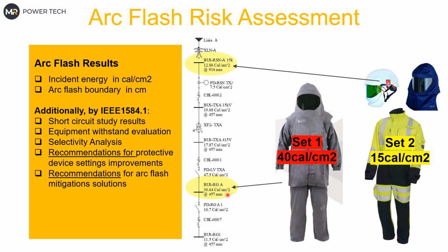So in practice, if we have 100 kilo amps or 50 kilo amps short circuit current on low voltage level, the arcing current can be something between 30% to 70%, which means it could be like 20 kilo amps. And sometimes for the protective device it's so low that it doesn't see it as a fault and has increased settings, or sees it as a fault but temporary, and increases the settings, and that causes the higher energies.